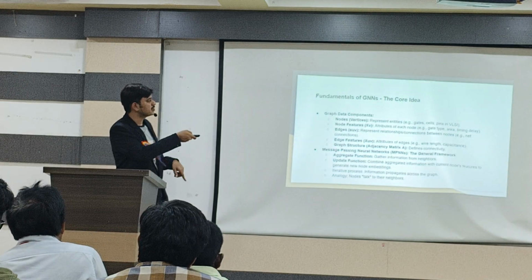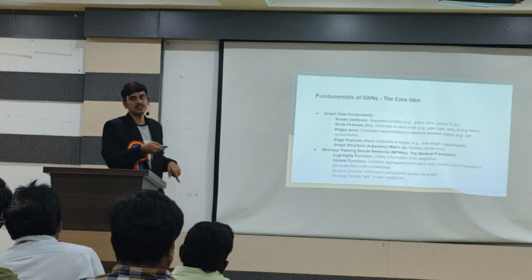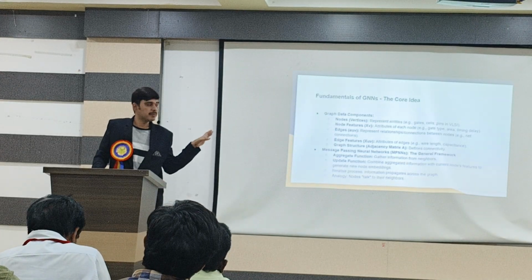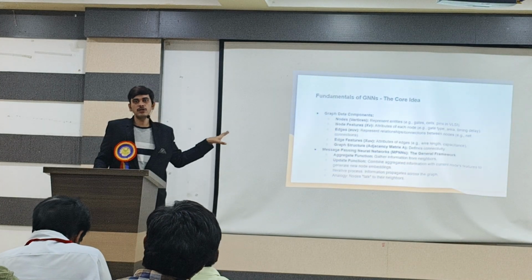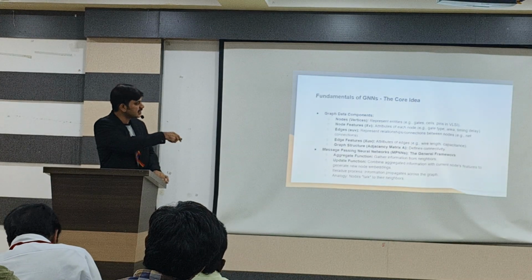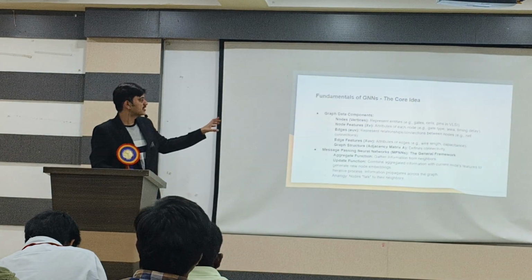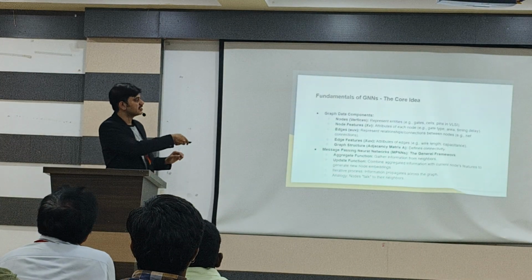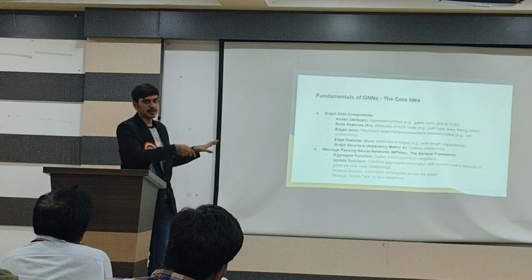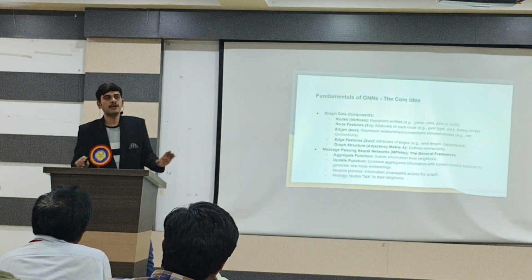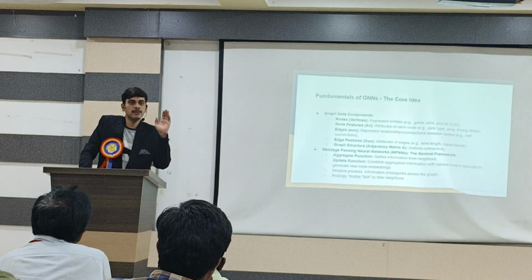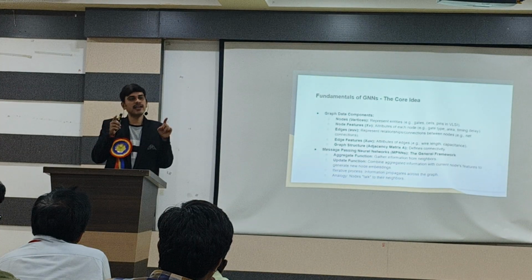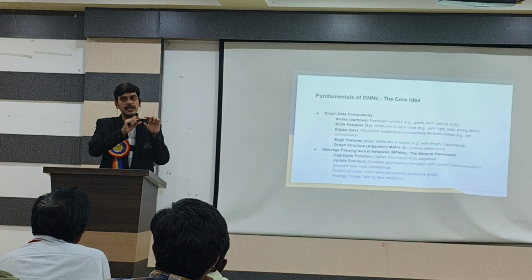The edges carry the relationship between the nodes, that is, the net and connection. Which buffer is connected to which inverter or gate, this information we have in the edges, and the analysis progresses based on this. Edge means it's a net, and the edge features are the properties the net has, like width and capacitance. We have two things in the net, input capacitance and output capacitance, and based on these two things we decide the delay of the net.